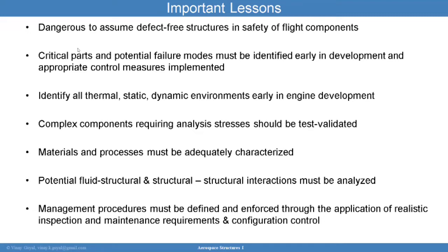You can use that complex-level testing at the smaller level to validate the analysis that can then be used to analyze the actual full-scale design. The analysis is actually very important. It connects testing to flight conditions, and that's where analysis can help: to evaluate the differences between the test conditions and flight conditions.